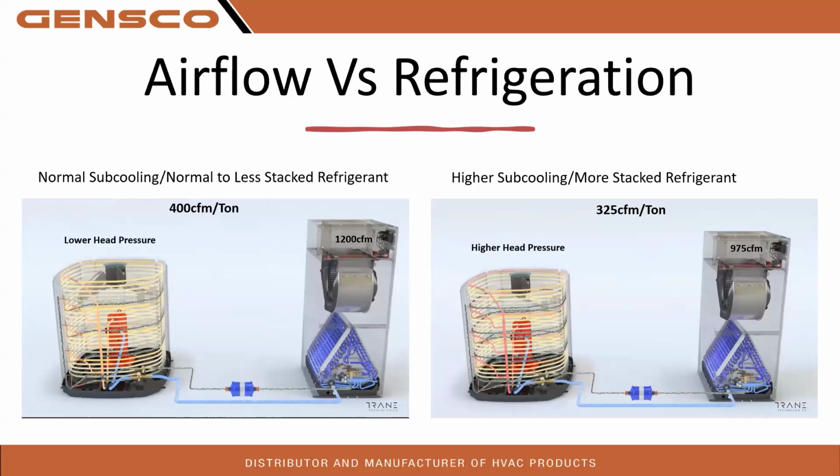When we have 325 CFM per ton, we're actually able to manage both sensible and a lot more of our latent load. Latent heat load is your humidity. That is literally the condensate draining down on a unit in cooling. When you get into areas that have high relative humidity, we are looking at a much higher latent load. So we'll go into a little bit more details on different areas. We'll go into a little bit more detail on what CFM per ton our target could be.